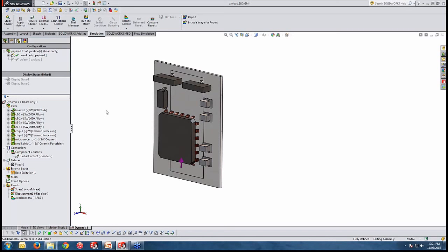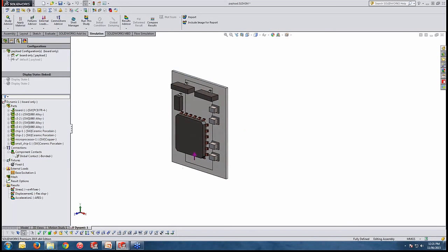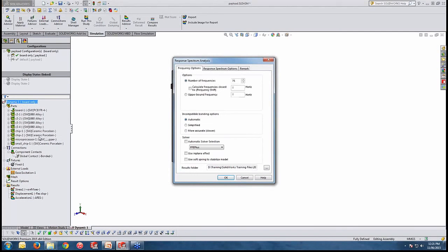As we said, it is very important to understand the natural frequency of such a system, and also the mass participation in the direction of collision. How can we do that? We need to perform a frequency analysis here. In order to do that, you simply go to your study properties and define how many natural frequencies you would like to capture with your study.